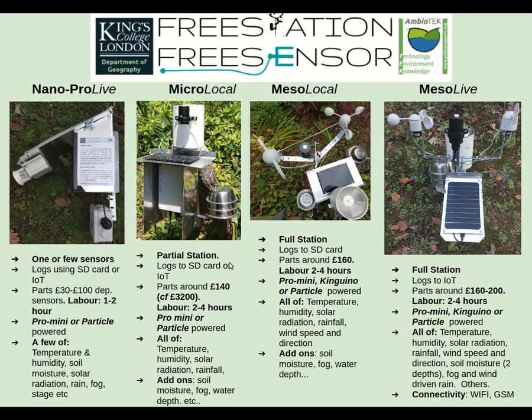Here are some example stations. We have data loggers that are just a few instruments, smaller like this. This one does temperature, humidity, air pressure and river stage using a sonar, through to full weather stations. And we have stations that are usable where there are no telephony networks, no 3G, no 2G. We call those local stations. They write to SD cards, and then we have stations that write their data directly through the internet. We call those the live stations.